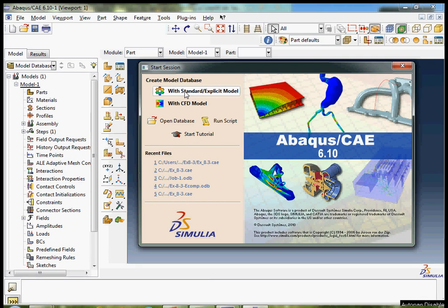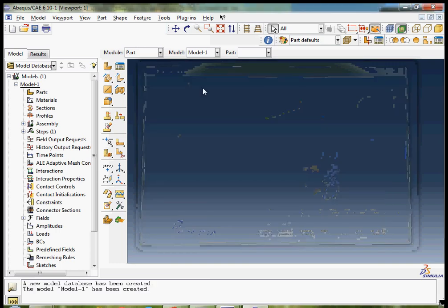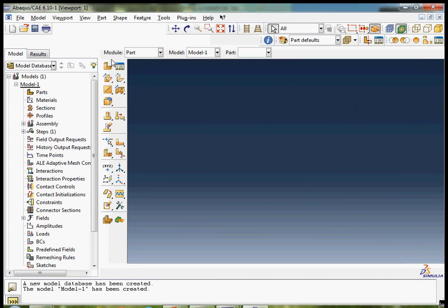The key difference is that one solves the system of equations based on explicit dynamic analysis, and the other one solves the equations implicitly. And that's actually the type of FEM that we are covering in this course. We are not really going to cover explicit dynamic based FE in this course. That's more useful for dynamic problems, for problems involving high rate of changes in the strains.